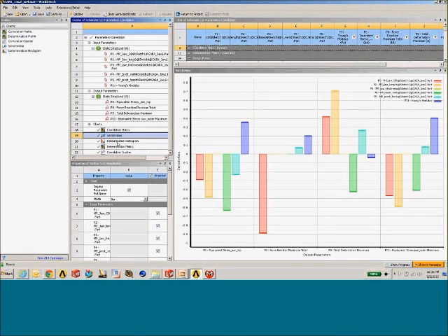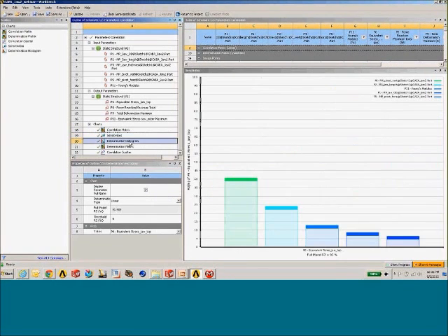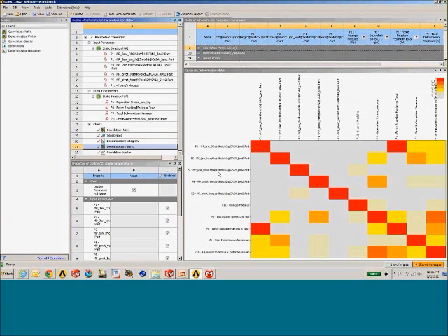Other things that we can look at, the determination histogram and the determination matrix, are measures of the predictive quality of these parameters and their design points. Looking at the histogram, we basically see the strength, the predictive quality here, and we can see that parameter 3, if I go through these, doesn't even show up on the list. So that's one that we're definitely going to eliminate. Parameter 5, again, being fairly weak. We're going to keep the remaining 4 parameters here. The determination matrix looks a lot like the correlation matrix, again showing predictive quality. So we're pretty confident here that parameters 3 and 5 are really doing nothing in terms of our predictive capability. We can eliminate them from any subsequent optimization or design of experiments analyses.